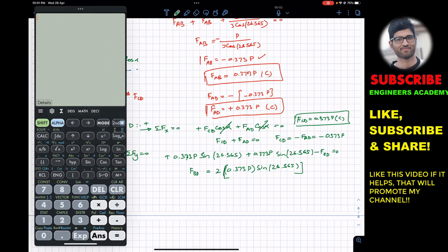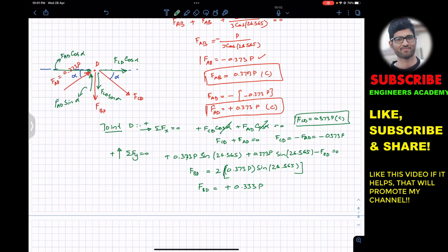So this gives me FBD equals plus 0.333P, and the plus sign indicates that the assumed direction is accurate. BD member is in tension. So this is 0.333P, and BD member is in tension.